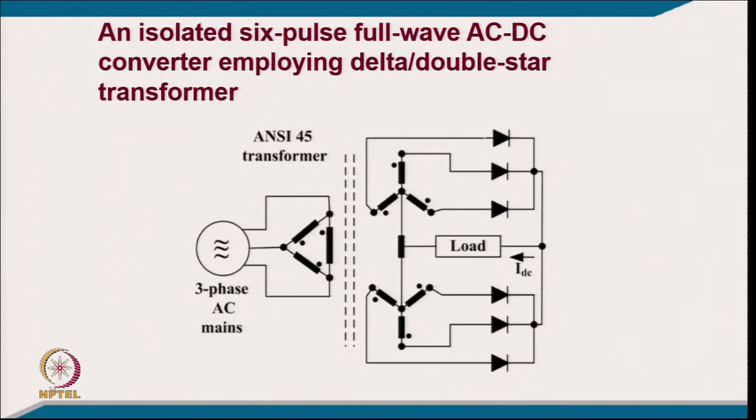So, one diode's losses are reduced. But when we are working at a very low voltage, a typical example may be 12 volt, the drop of one diode itself may cause losses corresponding to 3 to 4%, even more, for very high current and very low voltage applications. Even if you consider the diode drop to be 0.7 volt, 0.7 volt compared to 12 volt is not less than even 4% or 5% losses in one additional diode if you take a bridge configuration. So where losses are very important, especially in low voltage and high current applications, we prefer this.